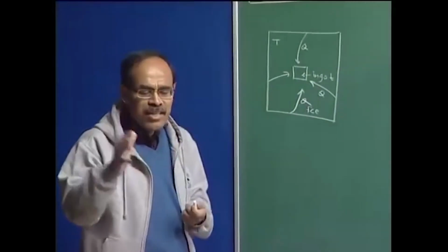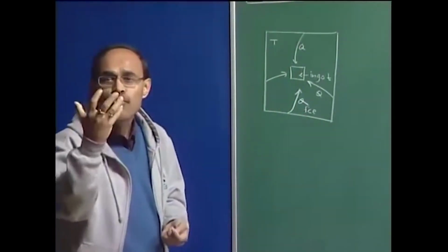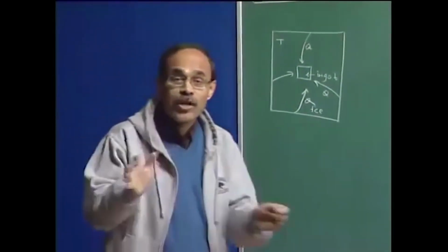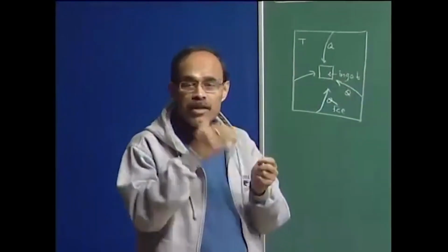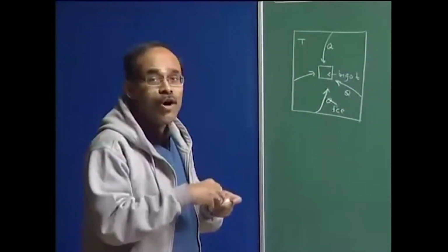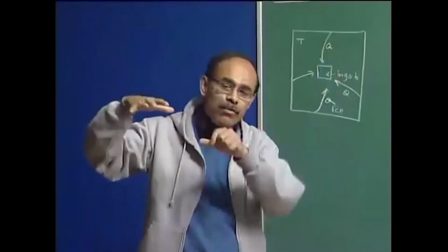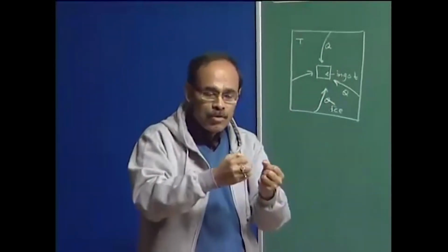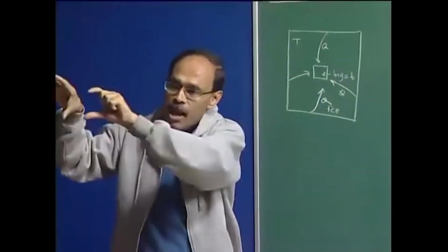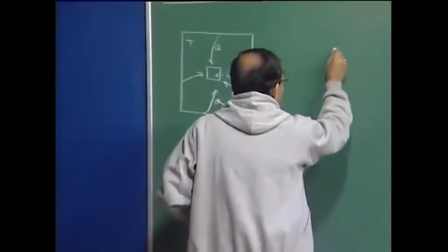So, innumerable descriptions can be given where heat transfer can be shown to play a decisive role. So there is no doubt that we will have to have a good background of heat transfer in order to tackle the efficiency of many metallurgical processes. Take the roll, and the slab is moving between the rolls. There is going to be a contact resistance, there is going to be heat flow, the roll is going to be cooled, and then the slab is moving between the rolls, and the rolls are going to take away heat.